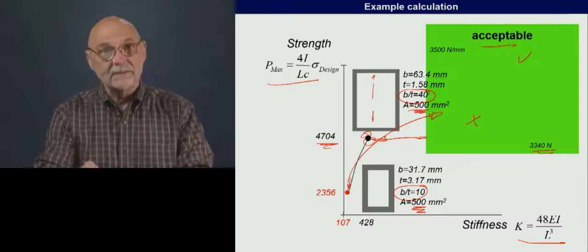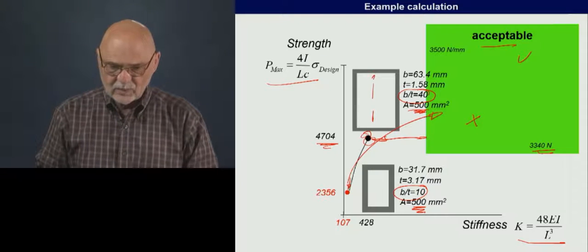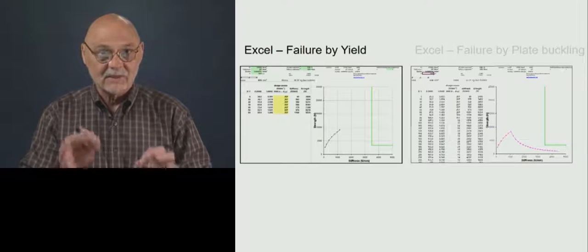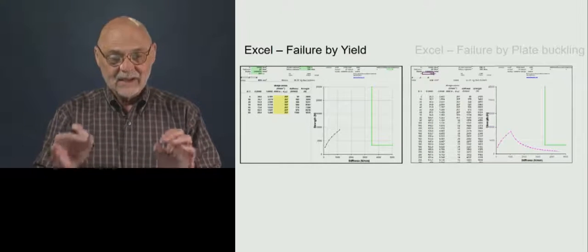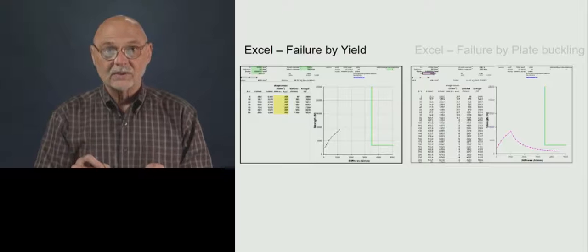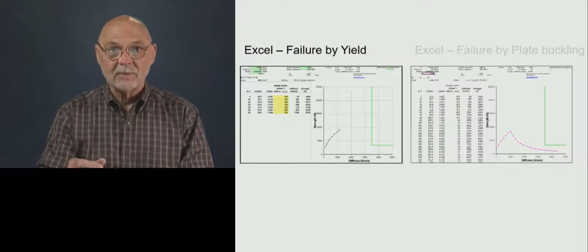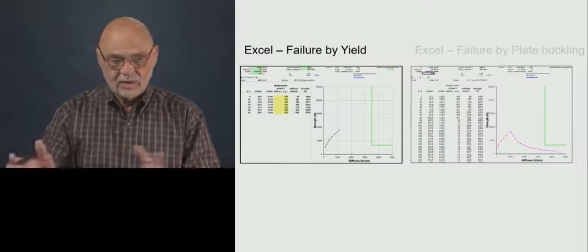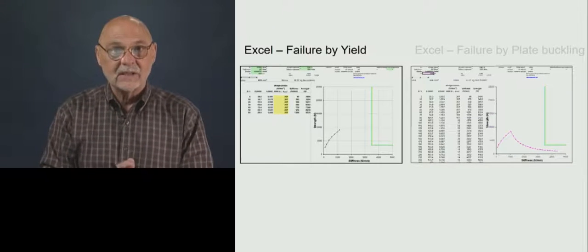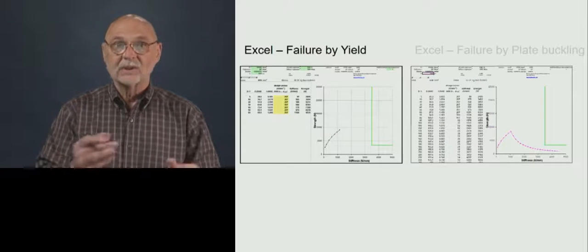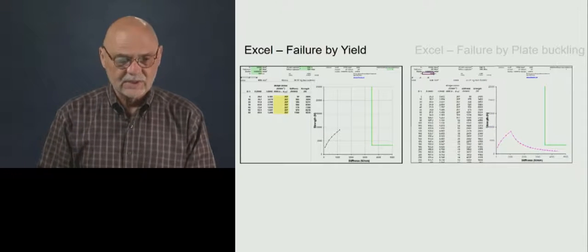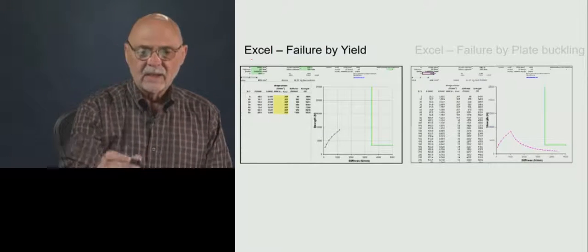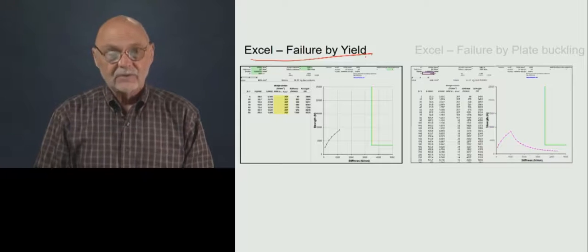Okay, so I hope you understand the model that we're looking at here. And the reason we're doing this again is to convince you that the optimal section will be a thin wall section for this little convertible example that has very realistic requirements that we're trying to meet. If we want mass efficiency, the best way to do it is not with a thick wall section. It's with a thin wall section. So what I've done is I've programmed those equations in Excel for two cases.